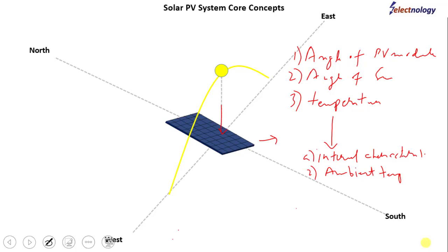Generally speaking, the difference between the power produced during the winter and summer season could be up to 10 to 15%, and this is a huge difference. So it's always preferable to have solar PV modules installed in a way that its temperature doesn't increase so much and there is a cool wind blowing underneath the solar PV modules that shall reduce its temperature.